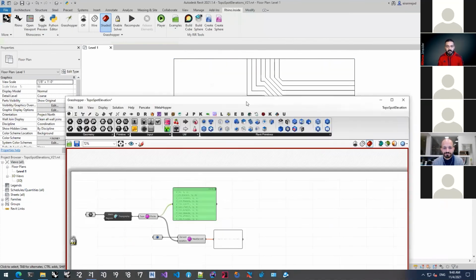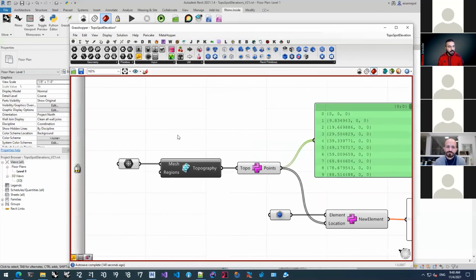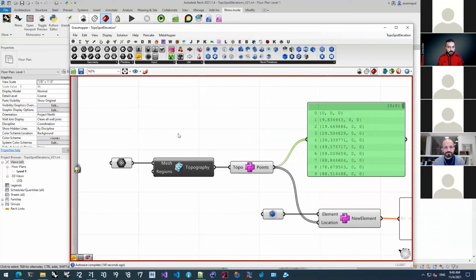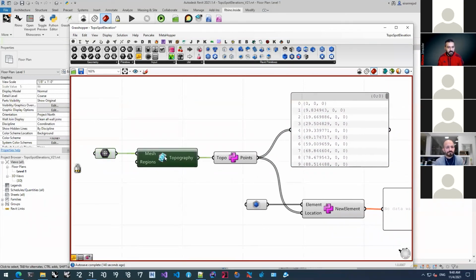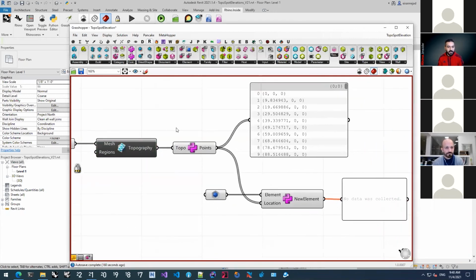Okay. So one of the weird things about the Revit API is that you kind of have to figure out where some things are possible or not. I'm grabbing the mesh from Rhino, passing it to a component that we have in Rhino.Inside.Revit for topography. I think it's under Site. Yeah, Add Topography from Mesh. So it creates that topography in the Revit model for me.